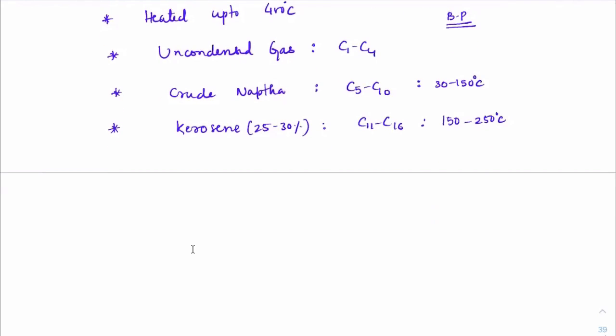And all the heavy oils, that includes diesel and more fuel oils, which we call heavy oil. Around 25 to 30% of that heavy oil, ranging between C16 to C18, will come around 250 to 400 degrees centigrade. The rest will be all residue wax. I guess this point is clear, everyone, right?